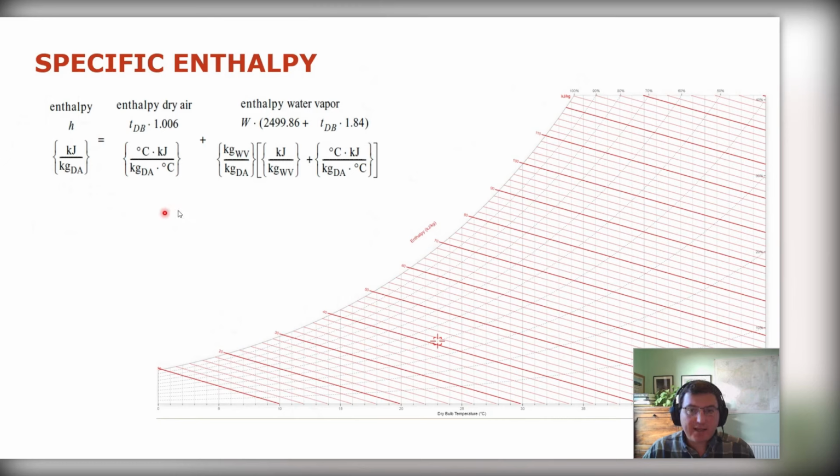So it's made up of the enthalpy of dry air plus the enthalpy of water vapor, and that itself is made from two things. It's the change that you have just in terms of heating up the vapor itself, which absorbs some heat, but the really important thing is this one here. See, that's the latent heat for evaporation. So evaporating any amount of liquid into vapor absorbs a lot of energy.